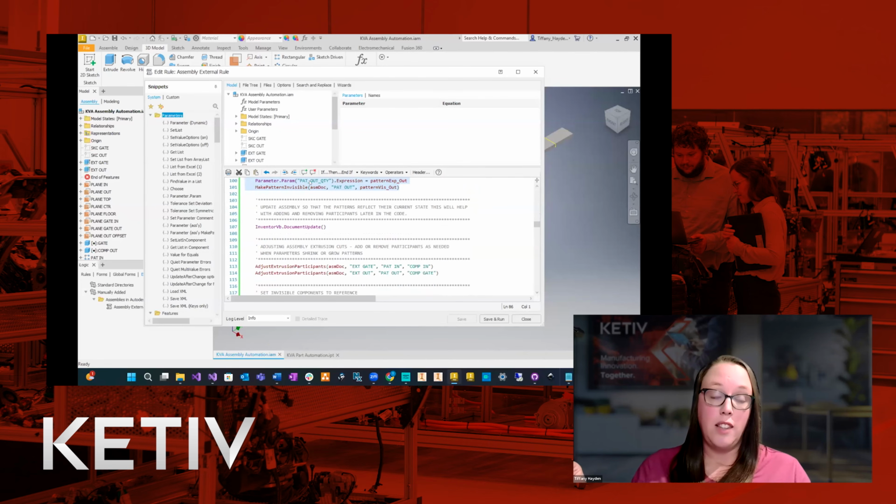If you're dealing with the assembly update after you affect patterns, and you want to accurately add and remove participants from an extrusion inside of an assembly, you have to do an assembly update after you affect the patterns. Because if you don't, it doesn't know that the pattern has changed and that you need to look at the very last one.